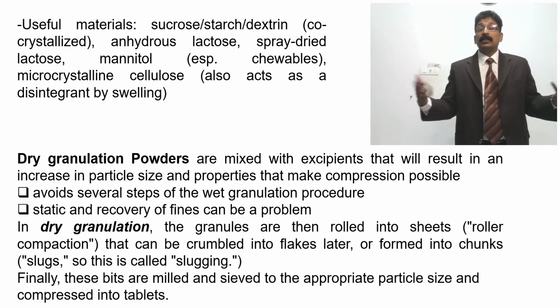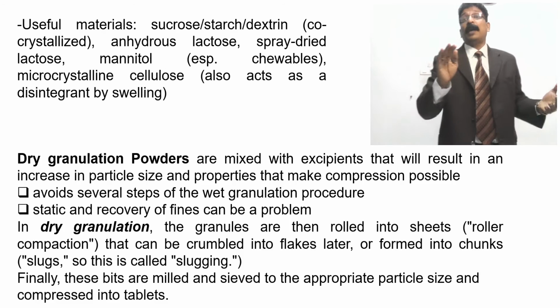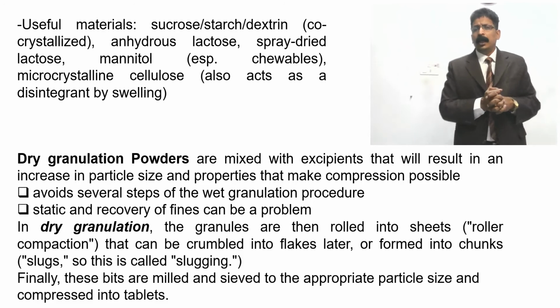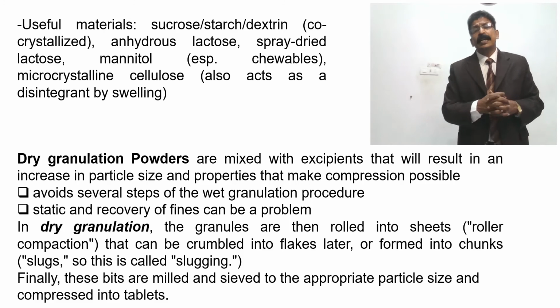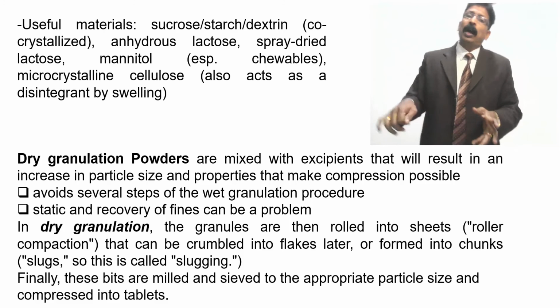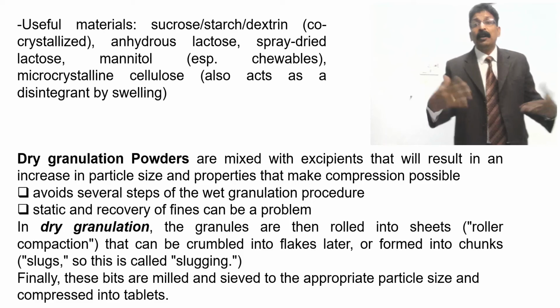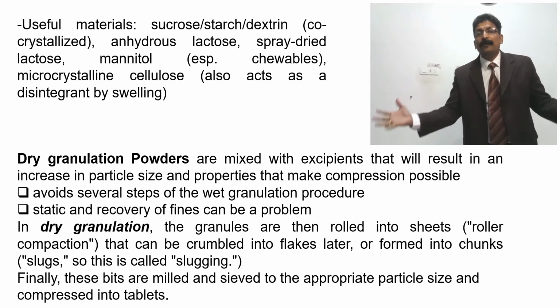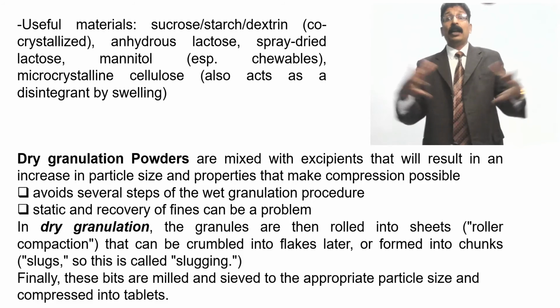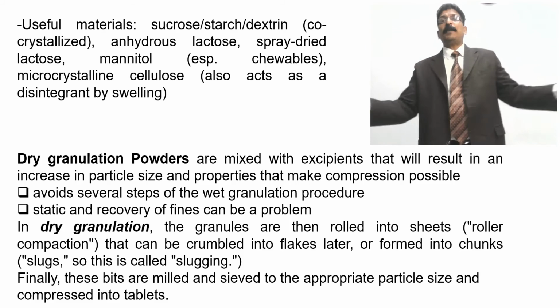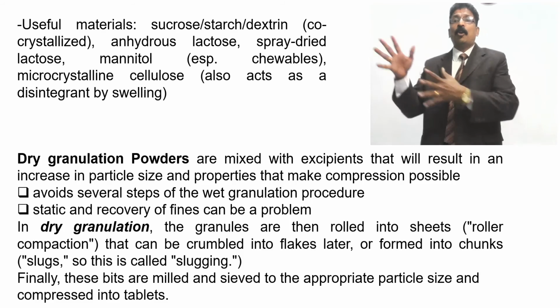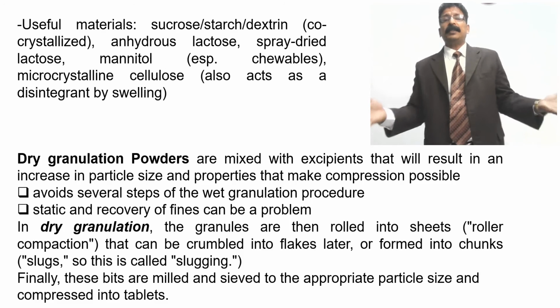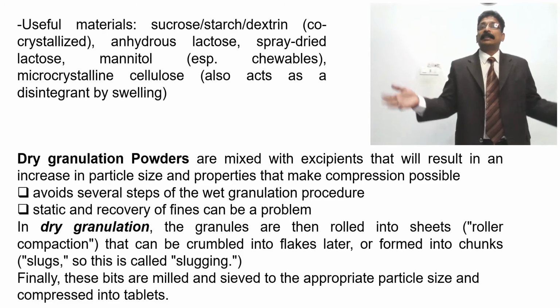Some other solvents which are acceptable for human beings can be used as a solvent, not only water. Usually starch paste and water can be added for binding. After binding and mixing, you go for a fluidized bed dryer and you get granules. When drying in the fluidized bed dryer, you get small granules and you maintain the moisture, how much should be present, because the moisture of the tablet plays a major role in disintegration and dissolution.